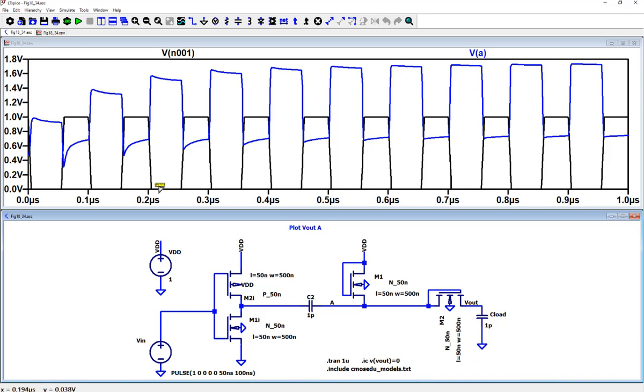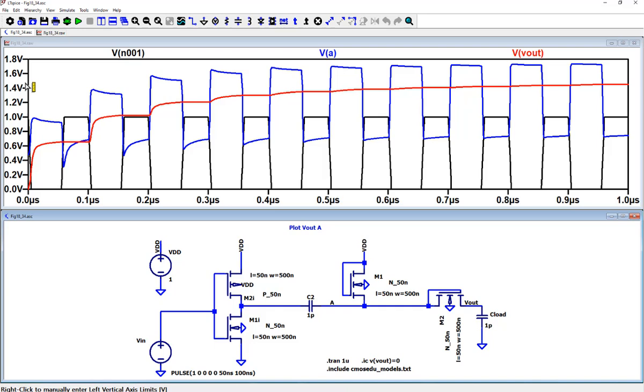You can see this one is definitely being lifted to VDD minus VTHN, right? So this is 2 VDD minus VTHN. This is 1 VDD minus VTHN. And eventually VL is being filtered and becomes a DC voltage. The VDD is a power supply. Keep in mind, the power supply is only 1 volt, but eventually you are generating a 1.4 volt DC voltage in the circuit. So that voltage will be higher than the voltage connected to the N wells because N wells are shorted to VDD.